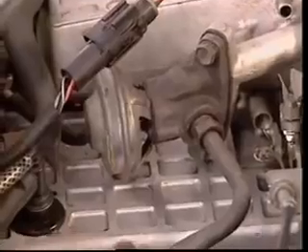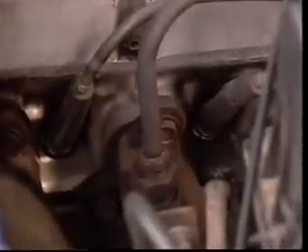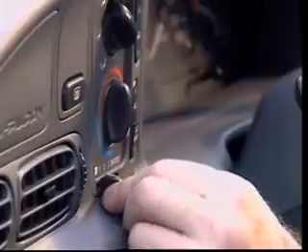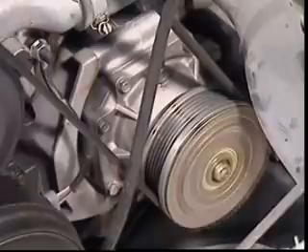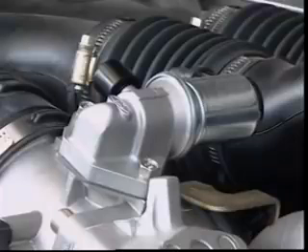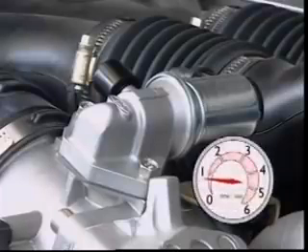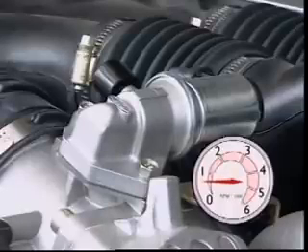Some exhaust gas is allowed to recirculate to control the nitrogen oxides. How much exhaust gas does this can be controlled by vacuum and vent solenoids in the vacuum circuit of the EGR valve. When loads are put on the engine, such as from air conditioning or lights, the control unit regulates how much the idle speed control valve opens to maintain a preset idling speed.